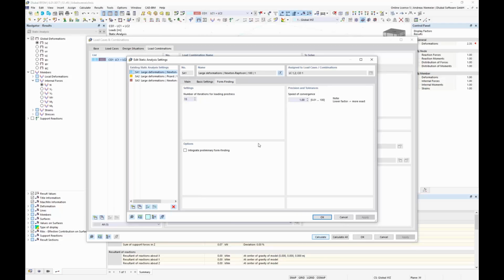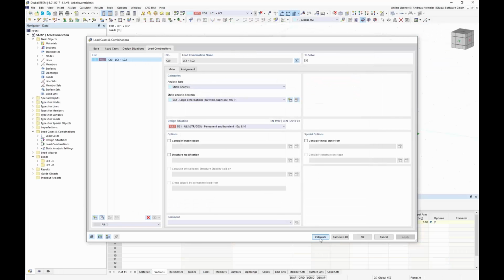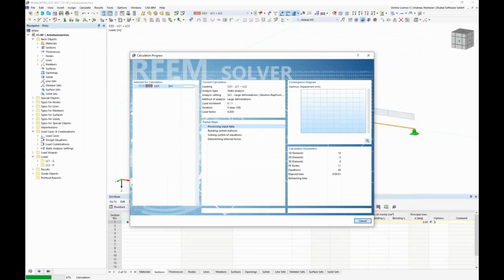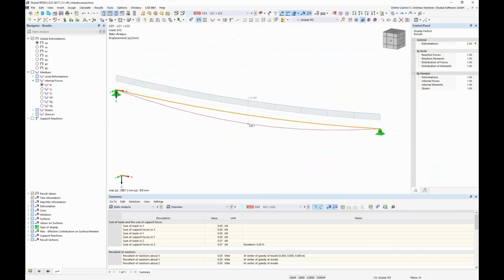You see there are fewer inputs. We simplified everything a little bit, and I increase now the pre-stress loadings to 50, and after confirmation and rerun we will get the 20 centimeters hopefully, and yes, we get it. So you see the program searched us this shape, 20 centimeters, with a corresponding force of 0.4 kilonewton.